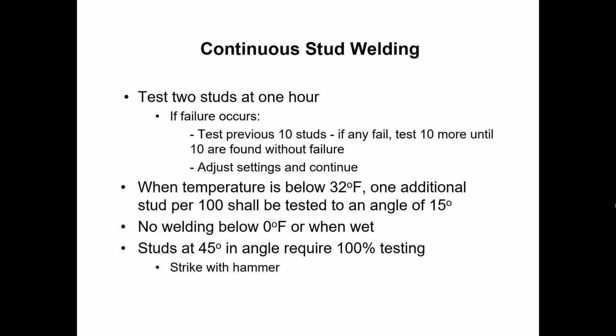When the temperature is below 32 degrees Fahrenheit, one additional stud for every 100 shall be tested to an angle of 15 degrees. So that's sort of nuanced.